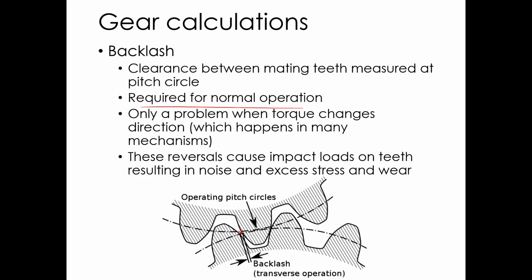So right now it looks like this gear is driving this one this way, and so they're touching right there, and this backlash is clearance right there on the back side. And you can see if I reverse direction of this gear here, there's going to be a time period where that gear accelerates because it's not loaded at all. It's just loaded by the inertia of that gear, and it's going to slam into this gear and reverse its direction. You can see that's going to be stressful. It's going to cause noise, wear, vibrations. It's going to cause problems. So we want it to be as small as necessary, essentially.